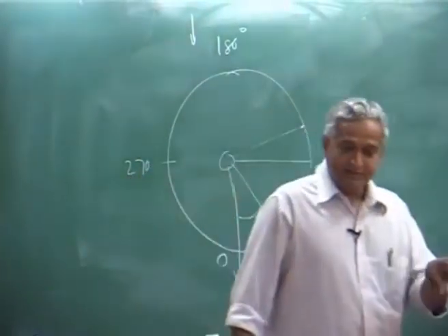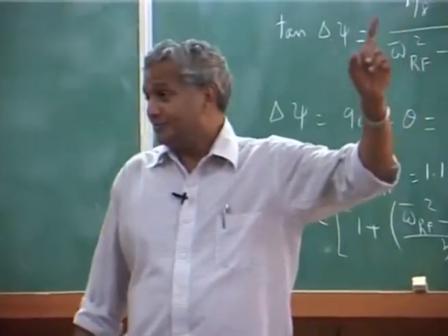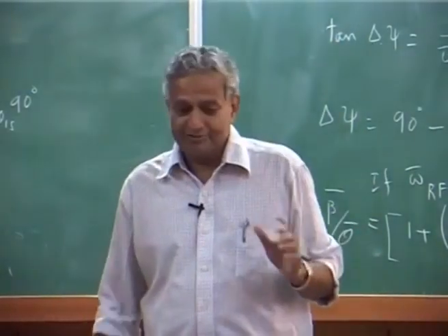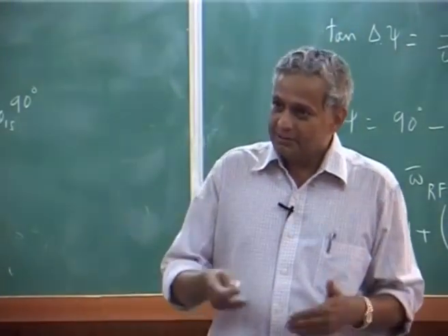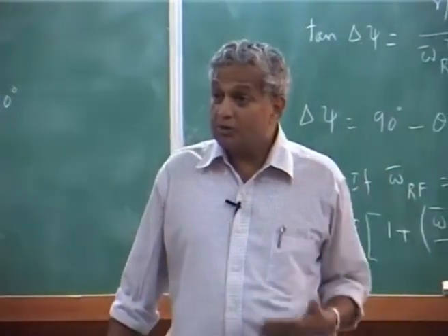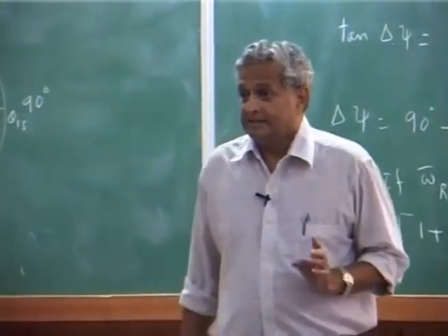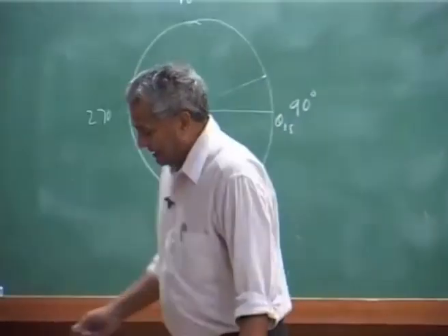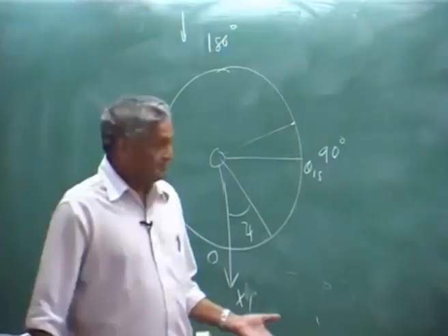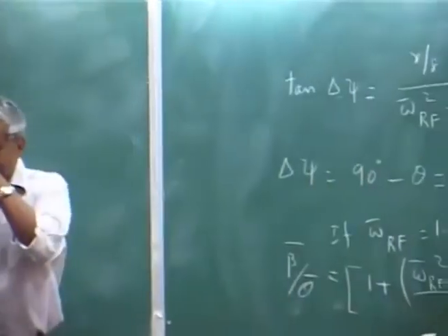Now, you imagine that design, the layout depends on what is your flap frequency. So, everything is linked, even your design, layout, many of these things are linked to flap. Otherwise, you are actually increasing the load of the pilot, because he still has to do a lot of control. Now, this phase angle, is it constant? That 72 degrees, whatever we got for this, is it fixed?